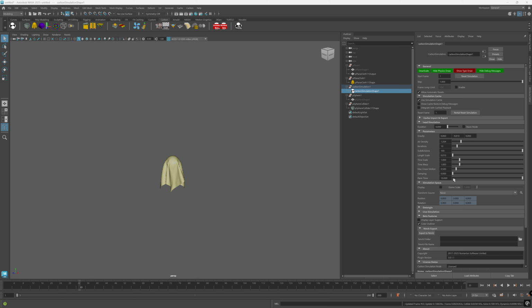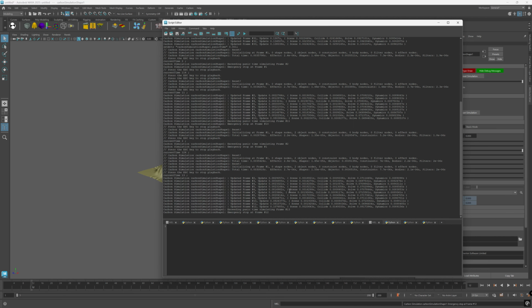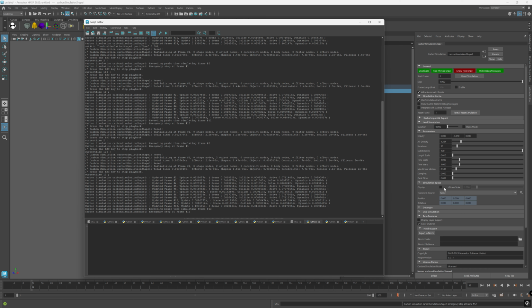Which means if we set our panic time to 1 millisecond, 0.001, it will trigger if a subdivision takes longer than 1 millisecond. Let's reset the simulation and run it. And here we are. Now it has triggered. Let's have a look where it triggered. It triggered on the last frame, which took over 100 milliseconds. So on average, a substep took around 1 millisecond and passed this threshold.